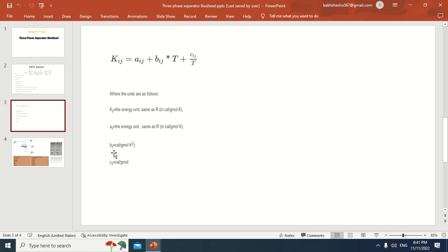And now I want to talk about the general NRTL. This variation of the NRTL model allows you to select the equation format for equation parameters T and X. Apply this model to systems with a wide boiling point range between components where you require a simultaneous solution of VLE and LLE, and there exists a wide boiling point or a concentration range between components.